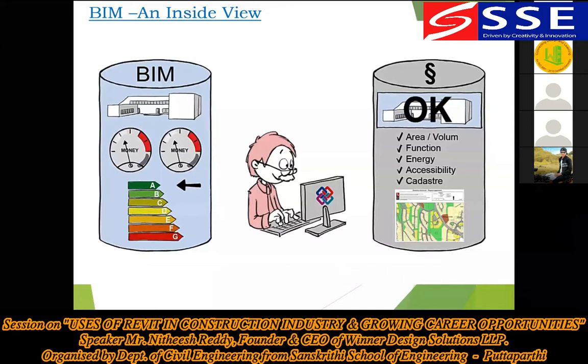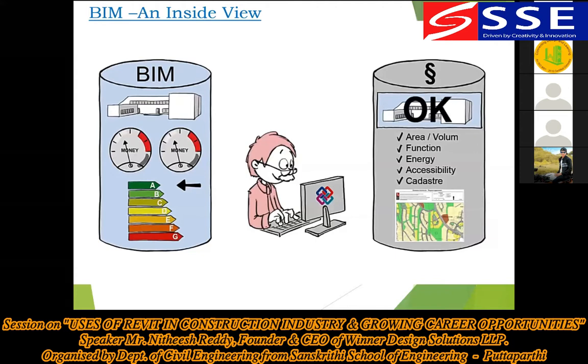So somewhere some other projects or some plugin support will be needed. Since AutoCAD file saving format is .dwg, the same way Revit has .rvt. Since both of these are from the company Autodesk, they have mutual exchange in importing and exporting formats. Now you have a STAAD Pro project, and you have an ETABS project. The ETABS project will not be supported to import into Revit, or the Revit model will not be supported to import into ETABS for analyzing.